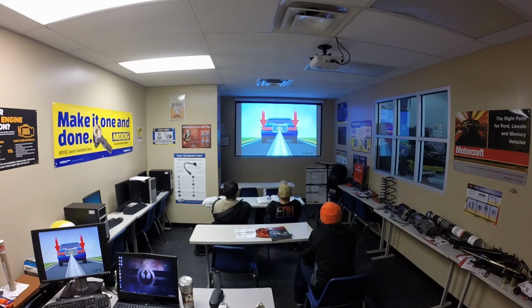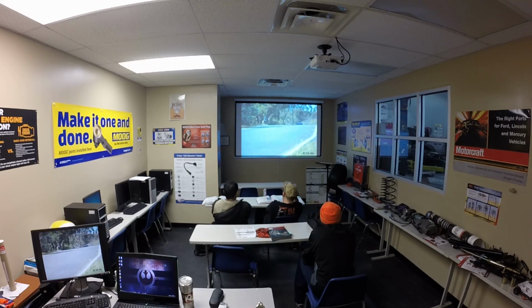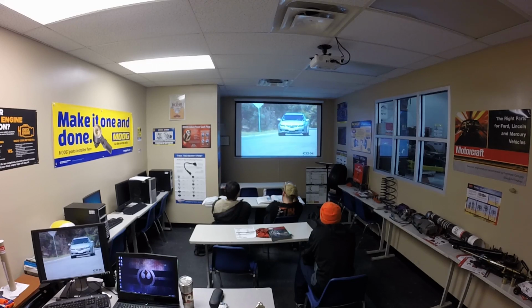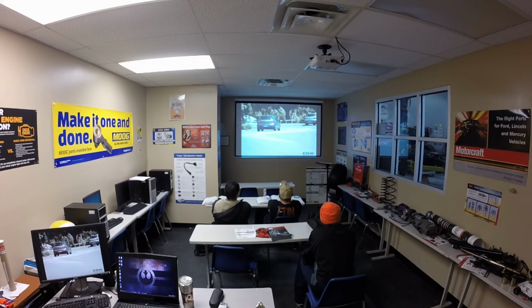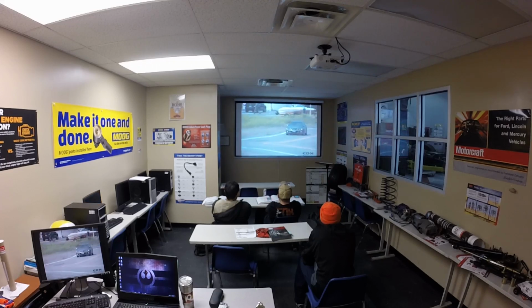Lateral weight distribution can be expressed in the same way. The height of the center of gravity is determined by the height of the mass above the road surface. Every vehicle has static weight distribution, whether it is at rest or traveling in a straight line at a steady speed. This is changed laterally by centrifugal force when the vehicle is turning, and in a fore and aft direction during acceleration or braking. During cornering, centrifugal force puts more weight on the outside wheels.